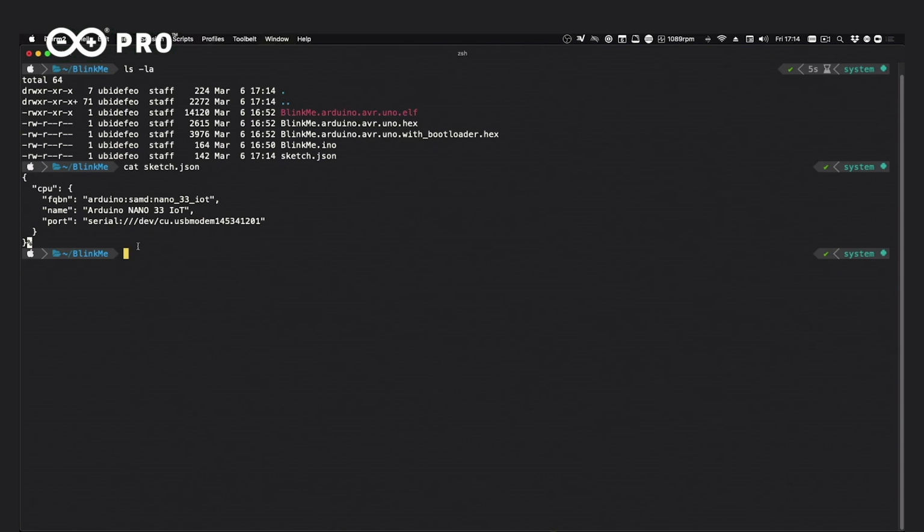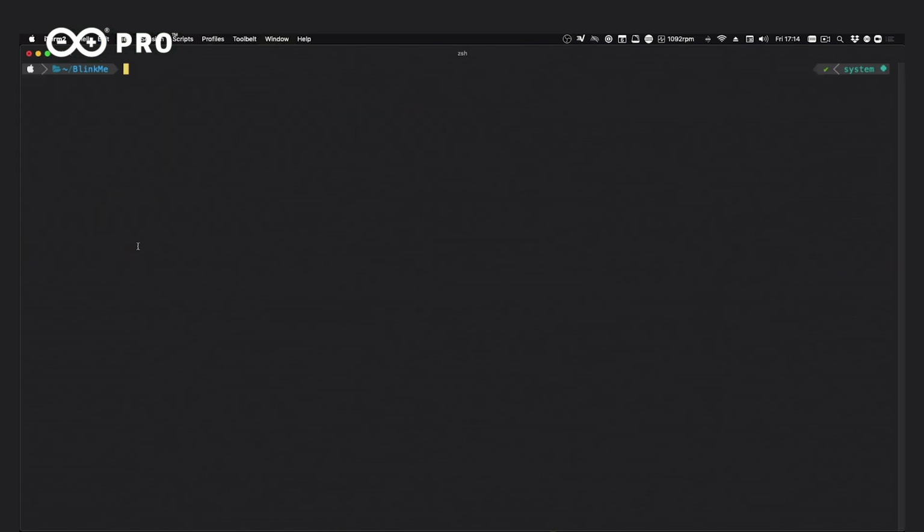So now essentially, remember when we earlier needed to run a series of commands, right? We needed to do arduino-cli compile -b arduino:samd:nano_33_iot in this case to compile the code, right? And right now we have an attached configuration.